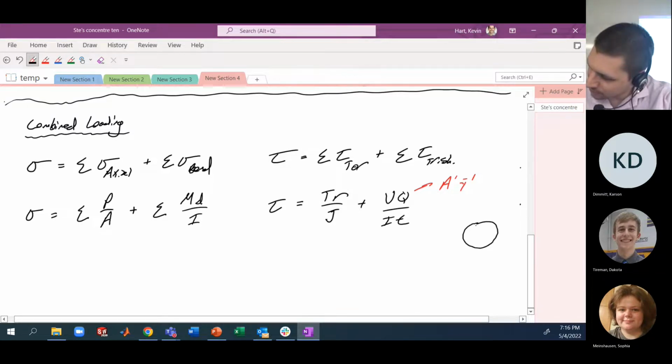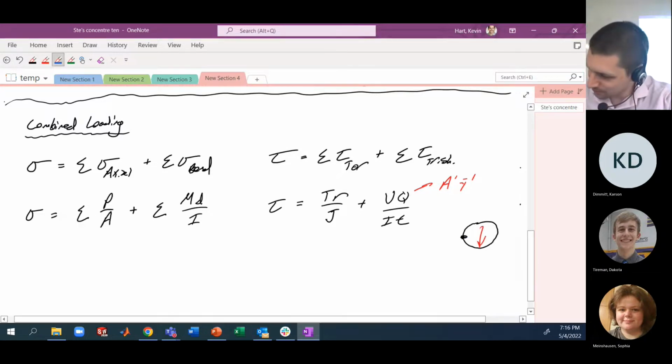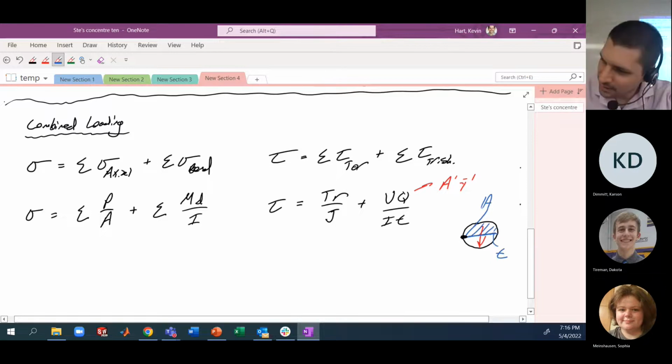And so if we just take a second for that idea, it's that, all right, for transverse shear, we got some point of interest here. We've got some load coming across the surface. Well, we want to split that particular cross-section at the point of interest, define that width at that particular location, perpendicular to the load as the variable t, and then the area above or below, doesn't really matter, is A prime, and then the distance from that line t to the centroid, which is here this Y bar prime.